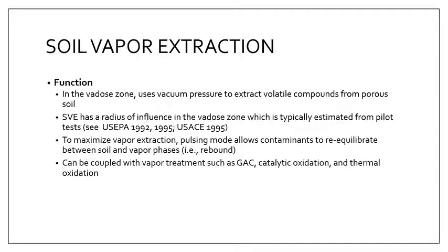All right, and its range of influence can be estimated from pilot testing, meaning you do one soil vapor extraction on site, and then you monitor the areas where the contaminants were actually extracted.